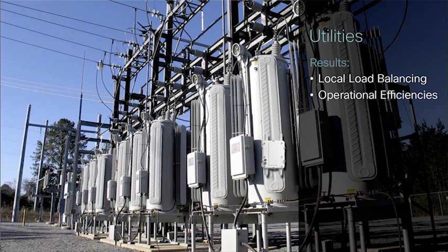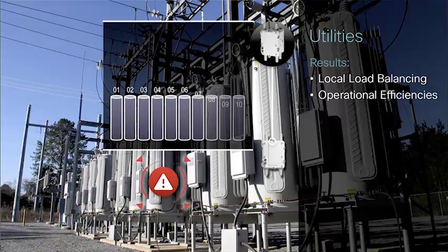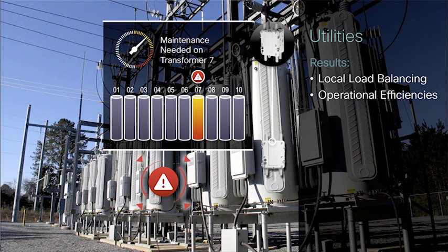IOX analyzes information from sensors connected to each transformer to constantly measure changing loads. By analyzing these things at the edge, customizable policies can automatically bring another transformer online when loads increase. If a transformer registers changes in behavior, IOX applications can disable it and notify a technician before a serious problem occurs. Speed is critical, as delays in information processing might result in major power failure or injury.